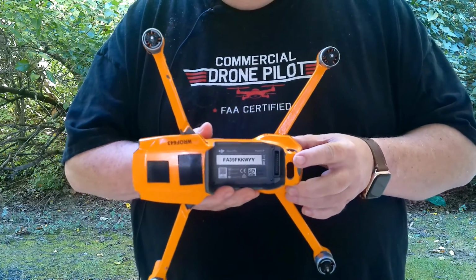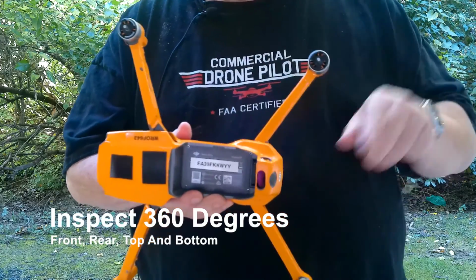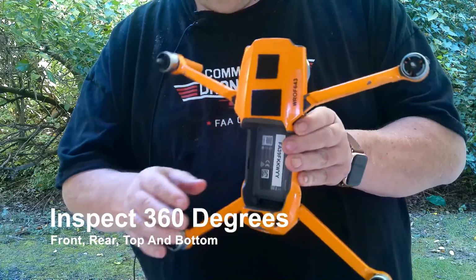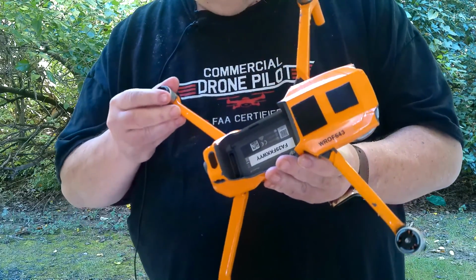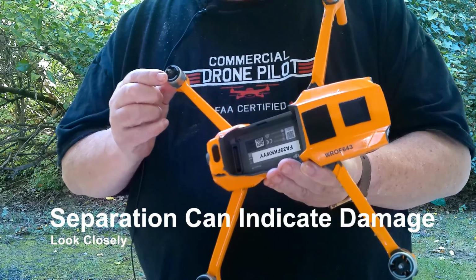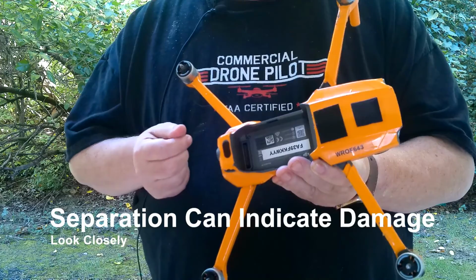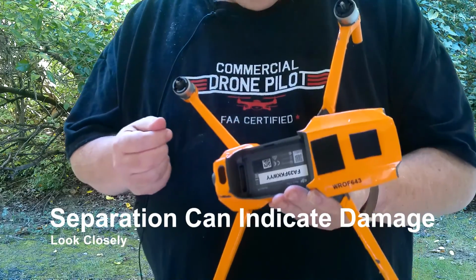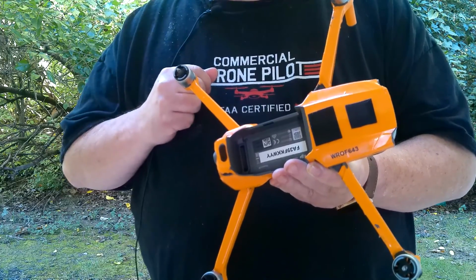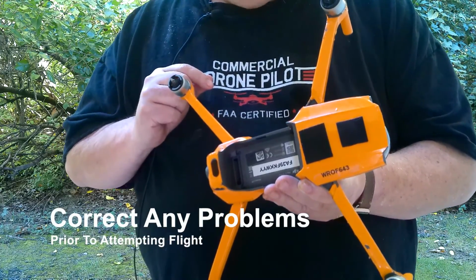Then we need to look at the outside of the airframe and do a 360-degree check. Pay special attention to where different parts come together. If they have received any type of force during a hard landing or anything else that you've encountered in flight, you may find that these pieces become separated, and that's a clue that you've got some structural problems that need to be dealt with.